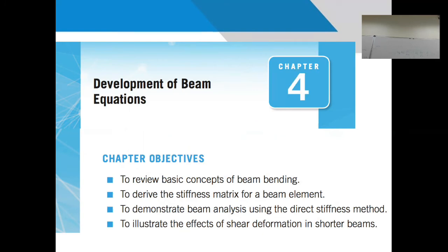What absorbed deformation is either in bending or shear. But for the beam, what dominates is bending. Right? No, you can neglect. Do you neglect the shear always? No. Which cases you don't ignore the shear? Concentrated load. Now about geometry of the beam. When you have a deep beam, which is short, with the ratio of length to the depth at a certain value, you cannot neglect the shear. It means you have to include bending deformation and shear deformation. Otherwise, your result is not going to be right.